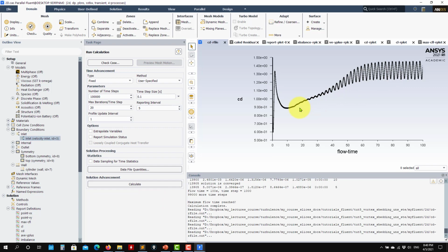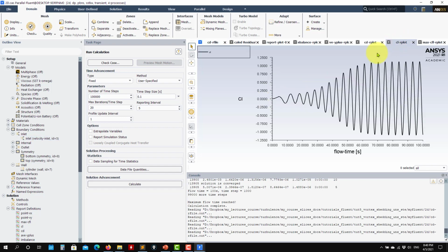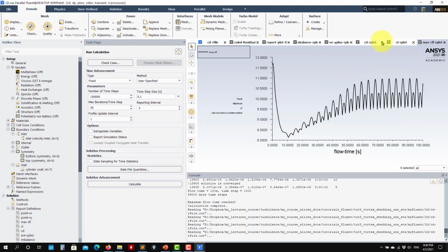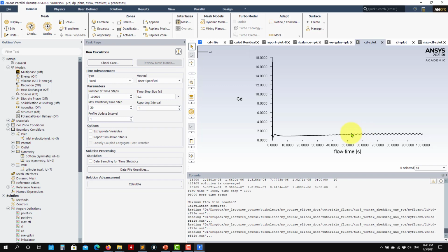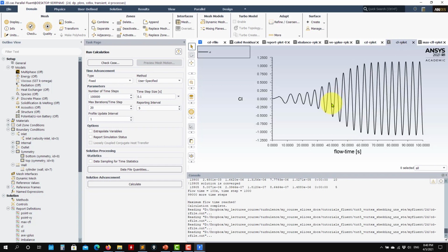The most sophisticated one is doing numerical tripwires, like what is done in experiments. So at a point in the domain, you can add a momentum, and that momentum will kind of blow some wind there to perturb the flow. There are many techniques, but I don't want to show you that. See that here you have all the signals, and clearly you can see that perturbation, that it takes a long time to unset that instability.